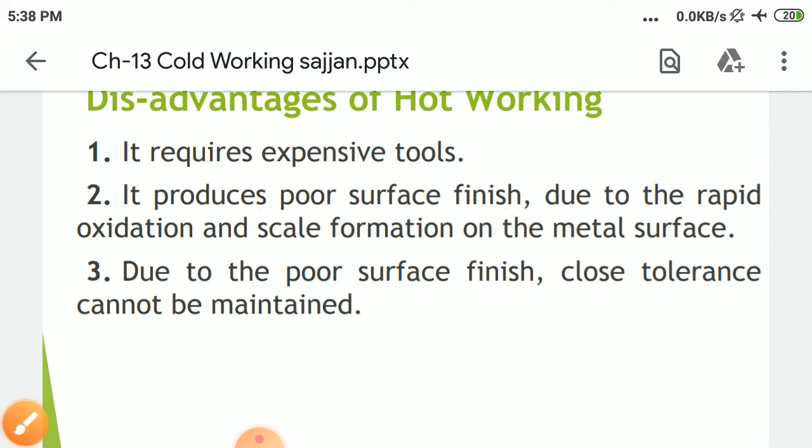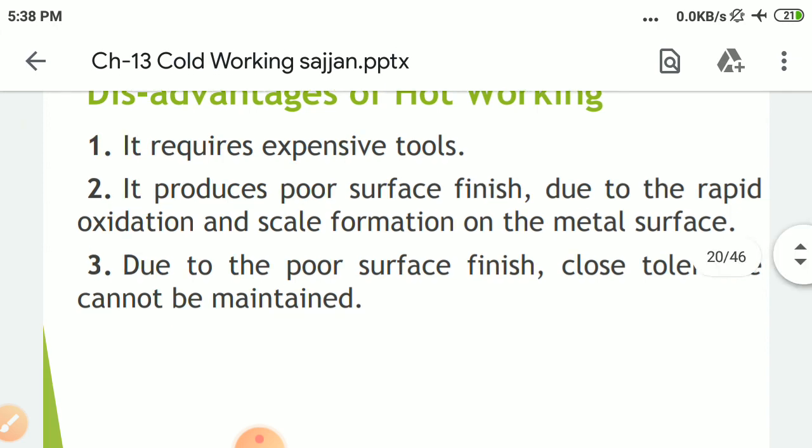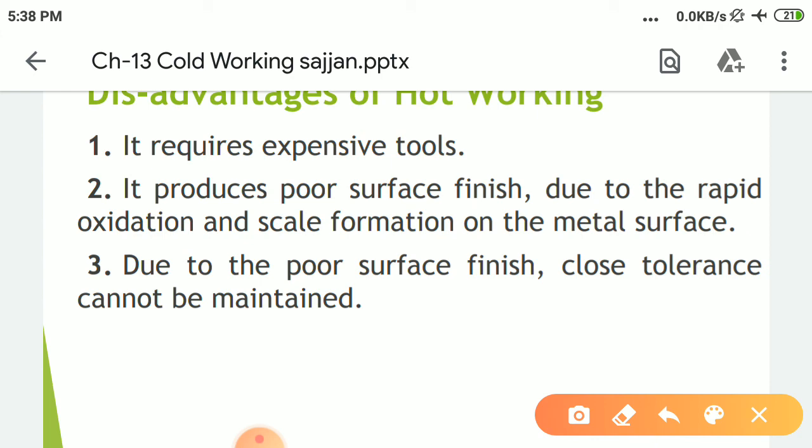Now due to the poor surface finish, close tolerance cannot be maintained. So what was the advantage we were having in cold working, like good tolerance? So here tolerance is not good. And there we were having good surface finish, here surface finish is not good. So you must remember these 2 points.